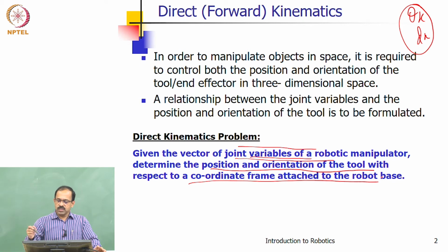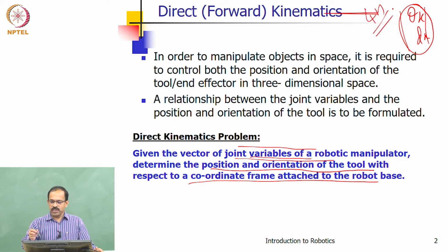So, what we know is theta, and of course, we need to formulate the kinematic problem in such a way that, though 4n parameters are involved in total, out of these 4n we have only n parameters varying. So, the other 3n parameters will be constant. If we know these 3n parameters, we can have a formulation where these parameters can be assigned, and then you will get the final relationship for the forward position of the robot. That is what we need to develop.